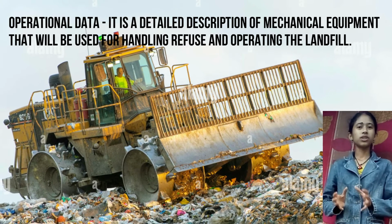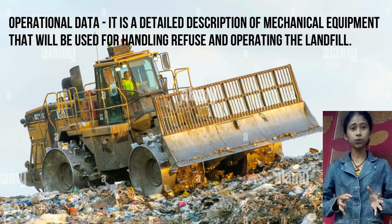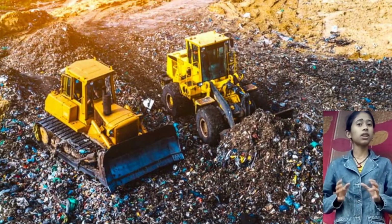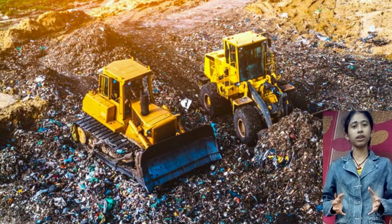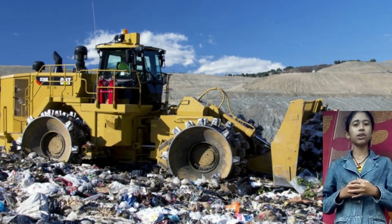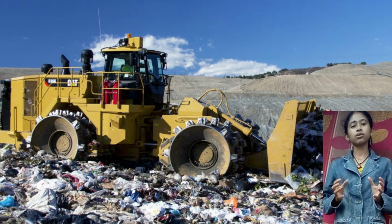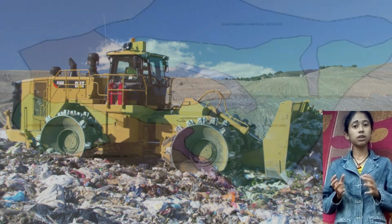Operational data includes a detailed description of mechanical equipment that will be used for handling refuse, operating the landfill, and the methods of solid waste placement. It also includes data on the solid waste for which disposal is required, including the types of waste, the amounts, and the varying delivery rates. If possible, the information should be based on the analysis of solid waste from where the project will be located, or from a similar project.